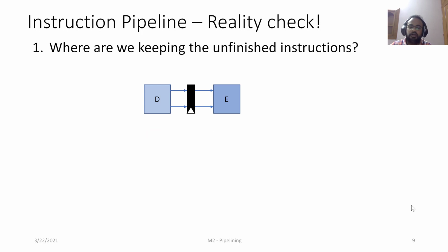The most straightforward answer is to introduce a small buffer, right? What is a buffer here? It has let's say 2 inputs and 2 outputs in this case, and let's say the values to its inputs are 1 and 2. It will sample these inputs only during the rising edge of the clock cycle, and the output will remain 1 and 2 during the next clock cycle.